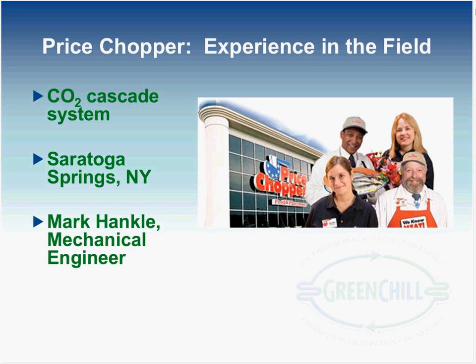Well, the secondary system that we did at Colony has a modular design on that low temp, and our refrigerant charge there was only 180 pounds for the whole low temp system on the primary side, versus a typical store where we'd have about 1,400 pounds. We haven't lost any refrigerant on that store, and that one's been open just over a year now, either primary or secondary.